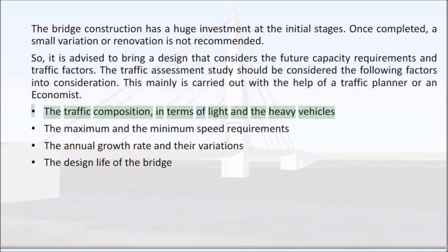The traffic composition, in terms of light and heavy vehicles. The maximum and the minimum speed requirements. The annual growth rate and their variations. The design life of the bridge.